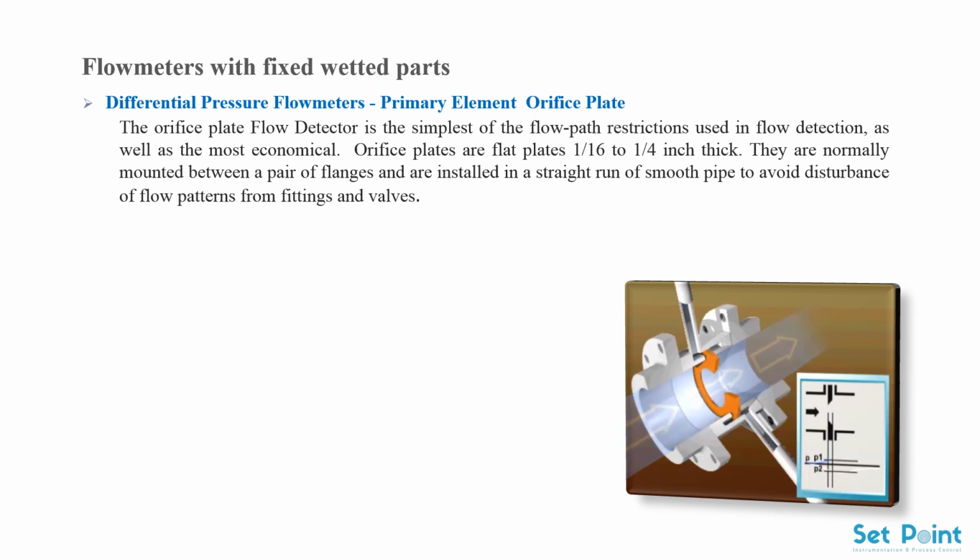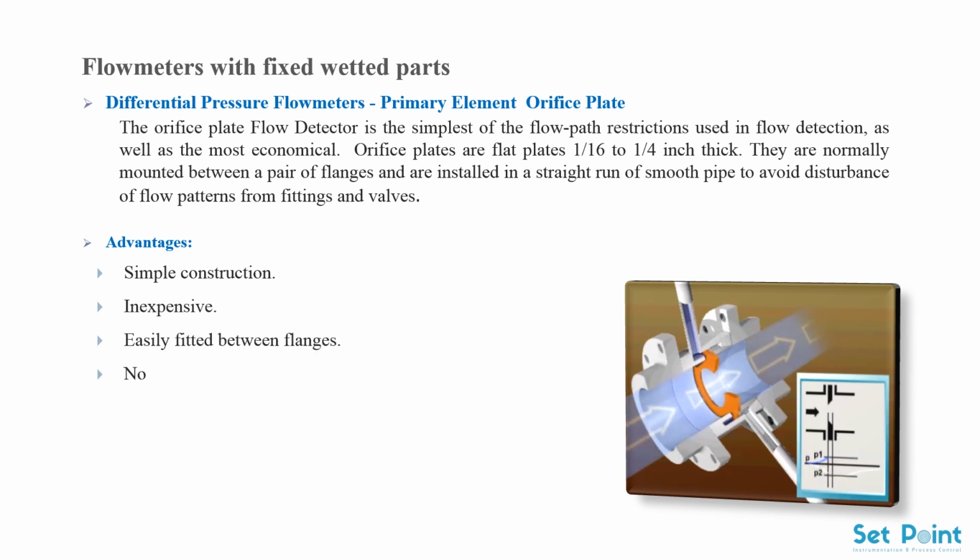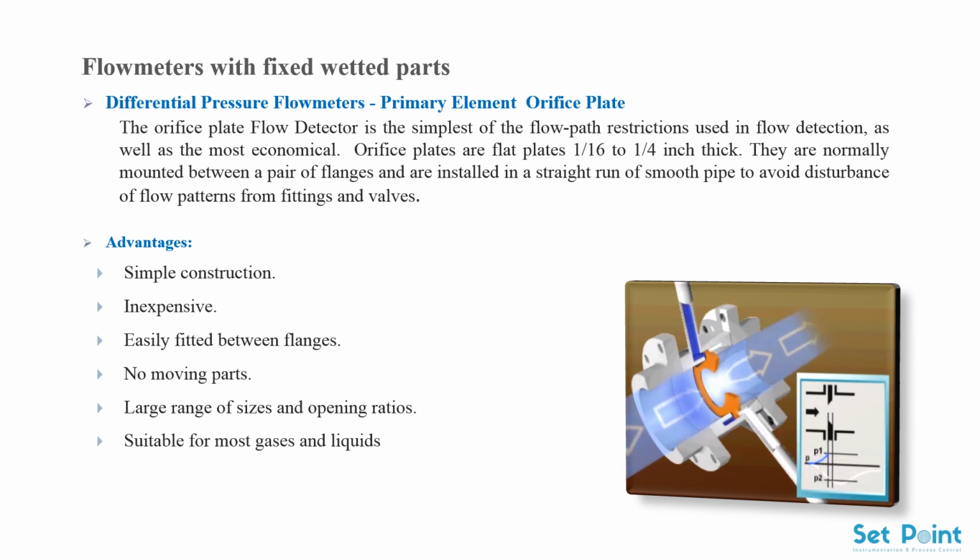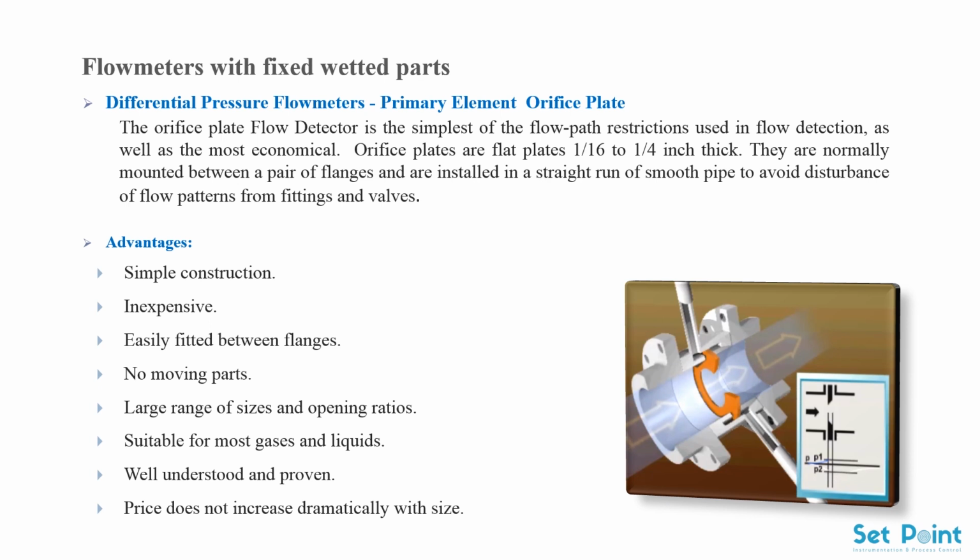Advantages. Simple construction. Inexpensive. Easily fitted between flanges. No moving parts. Large range of sizes and opening ratios. Suitable for most gases and liquids. Well understood and proven. Price does not increase dramatically with size.